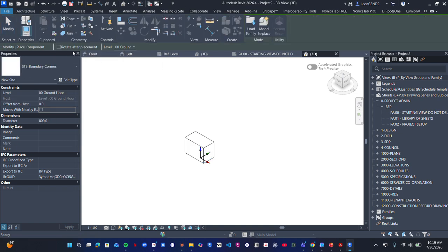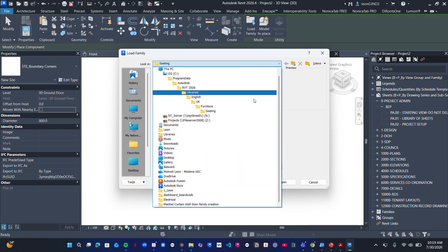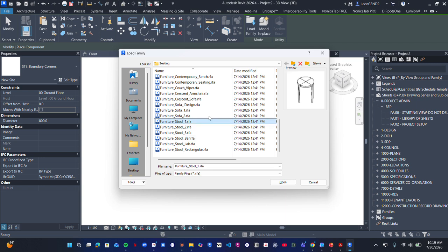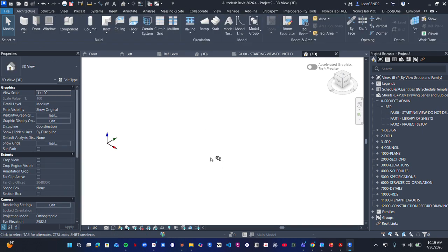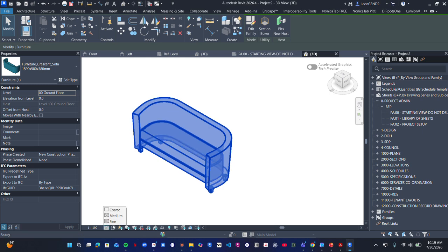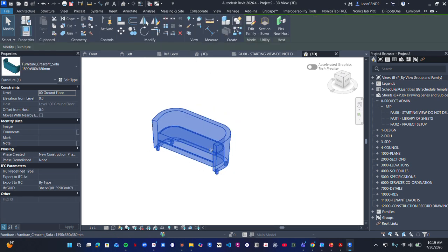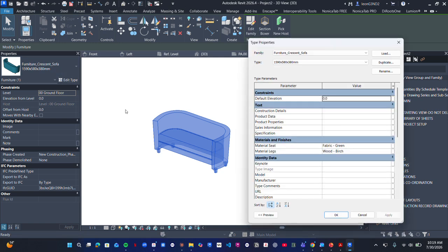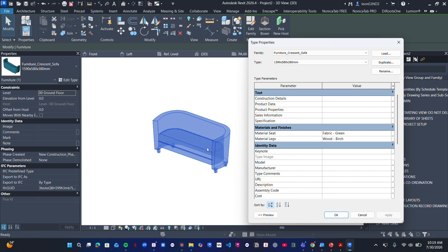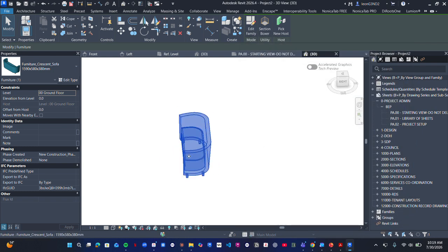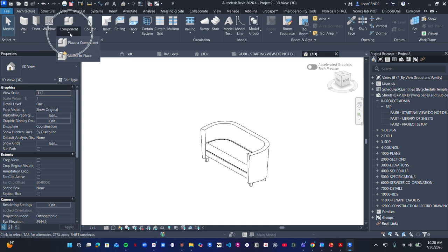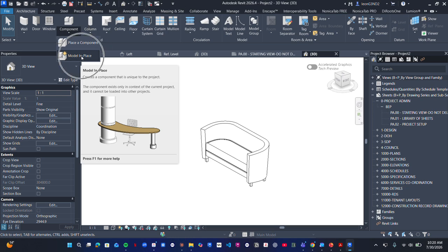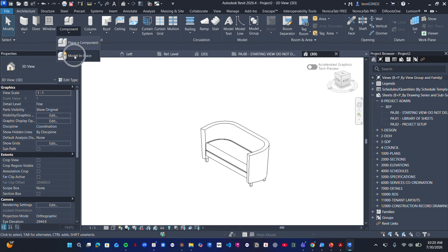So if I come here, the whole reason behind why we have families is that we are lazy in a sense, and we like to have furniture that we can add to any model space that we'd like to add it to. For example, like this. Just like this here, say fine, say 1:1. So this family now has its parameters that are preset here and developed. And this family now is addable to any sort of Revit model space, as opposed to just being native to a specific model space, like this model in place component tool. So this is usually good for specific furniture types. You can see here there's the preview that you are developing, like I said, with kitchens, etc.